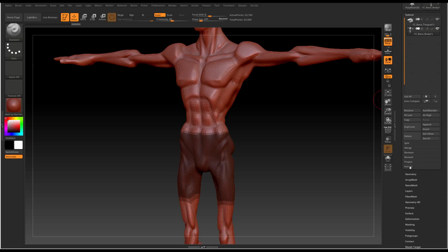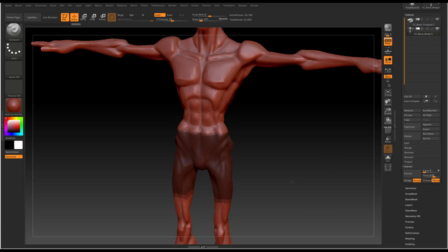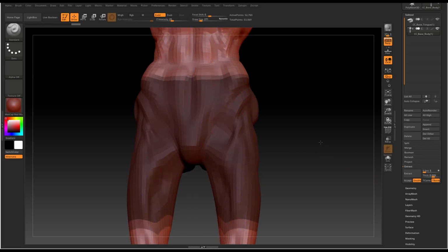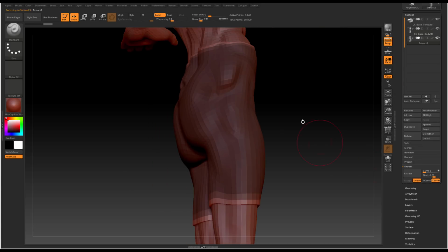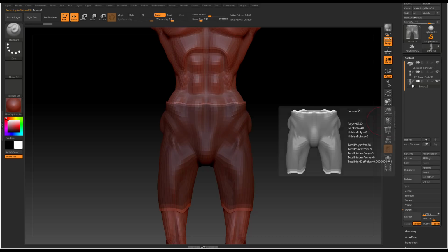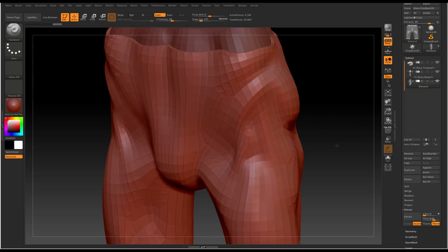Next, I'll perform extract from under the subtool menu. When you click on this button, the mesh extraction is actually just providing you a preview. Under the current settings, the extraction will be too thick. So I'm going to dial this down to about 5 millimeters in thickness. And hit this Accept button to make the actual extraction mesh. Clear out the mask and then we can make corrections to this base mesh.